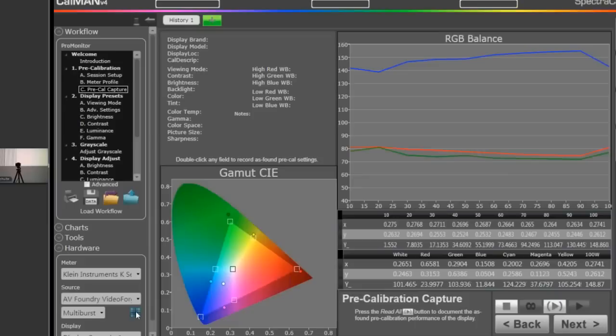And coming into the display's picture adjustments, for the aspect ratio on the display, there are a number of settings. 16:9, first of all, is the default setting. You can see in the upper right-hand section of the screen right now, this is the area where on the test pattern we have the fine resolution portion, 1 pixel on, 1 pixel off, white, black, white, black stripes.